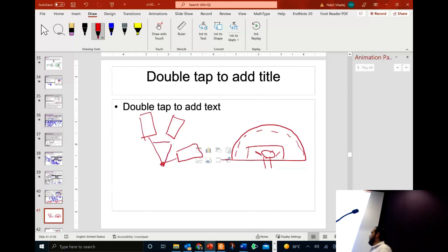So the magnetic field, due to this very strong current flowing through the strobe light, was inducing a current in this ground loop, and this board was always turning on. So this is induced voltage, induced EMF in this PCB board due to the changing magnetic field. So what we did, we disconnected this PCB board and we soldered the wire to this common point here, and it took care of the problem.